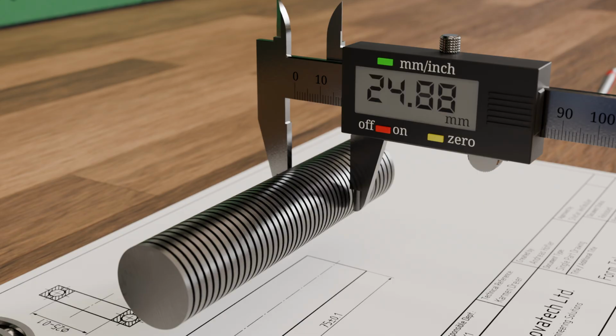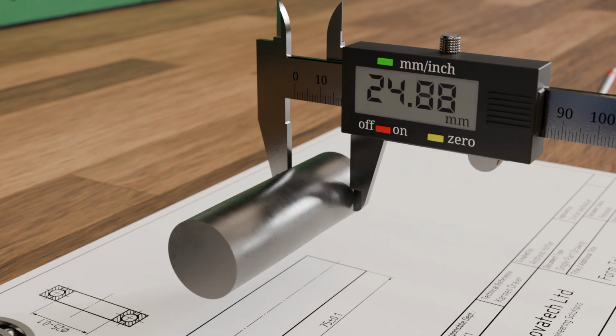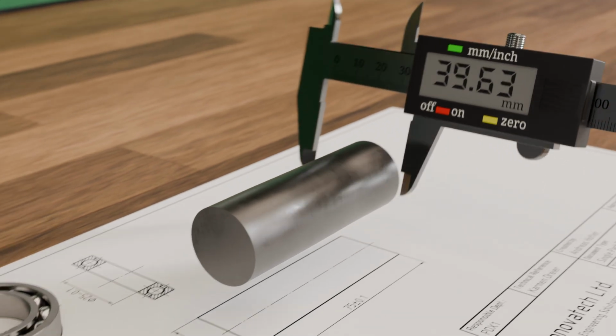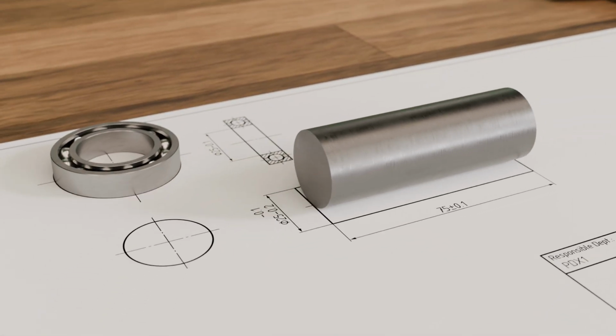In the case of a curved shaft, the discs no longer lie on a straight axis, but on a curved one. This example therefore makes it clear that it is generally not sufficient to specify tolerances only for dimensions, but that tolerances for form deviations must also be specified. In our case, it would therefore be sensible to specify a maximum permissible deviation from the cylindrical form. The specification of such a deviation of cylindricity will be explained in more detail later.